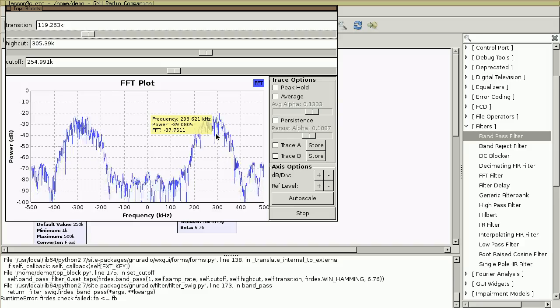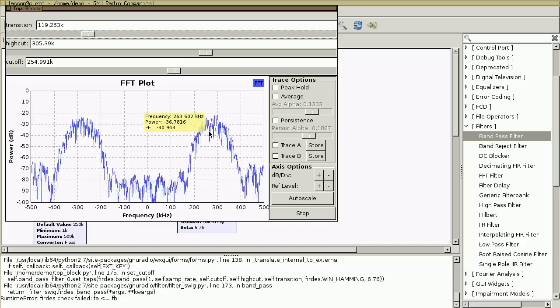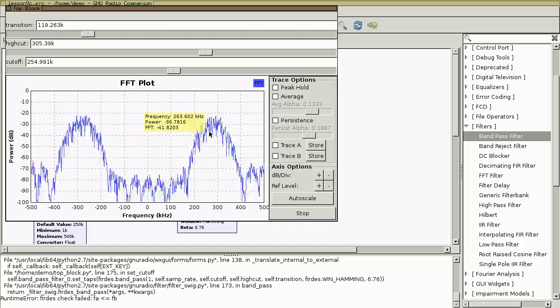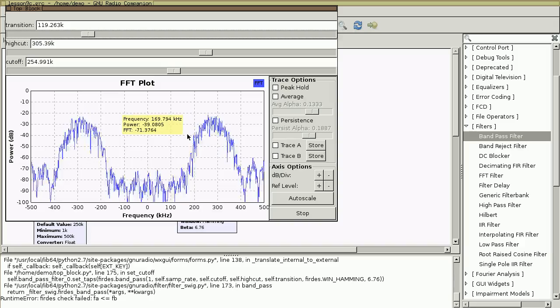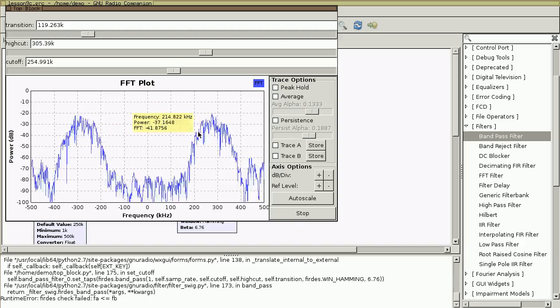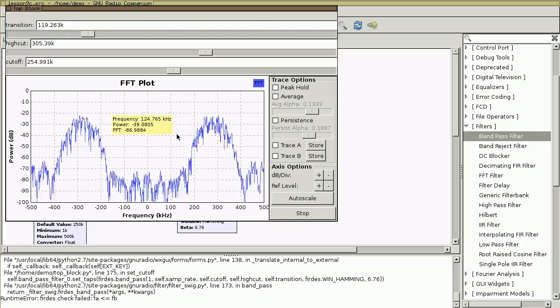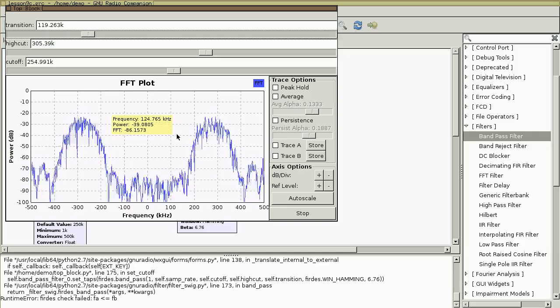How do we make a signal capable of describing both positive and negative frequencies and have them be different from each other? Well, the way we do that is with complex numbers, of course. So what we can do is actually change our block. Instead of having real value taps, we can change it to have complex valued taps.